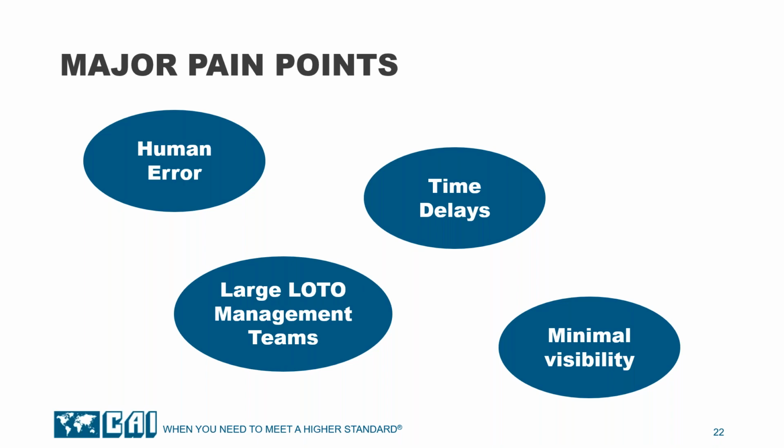When we have that, lockout tagout planning and lockout tagout execution. Planning, hey, maybe I forgot about a node, or in the execution I should have locked out this node and instead I locked out this node over there, but it's fraught with human error. Time delays. In a construction site, and especially in this data center site that I'm going to show, they spend hours determining what the lockout tagout plan is going to be.